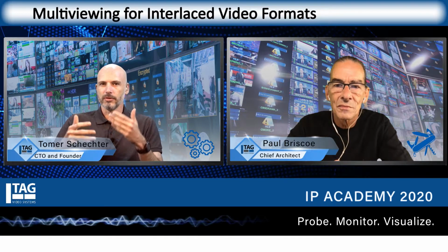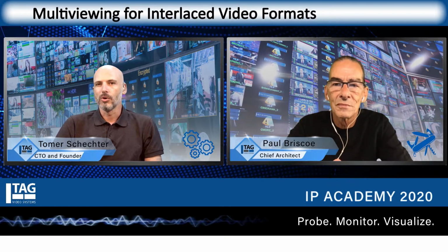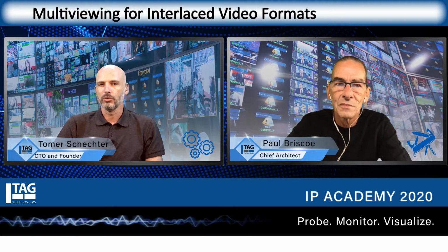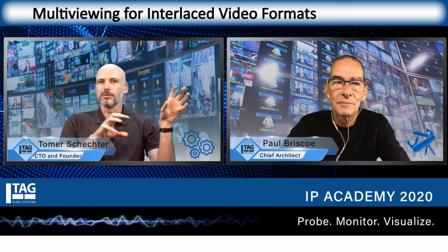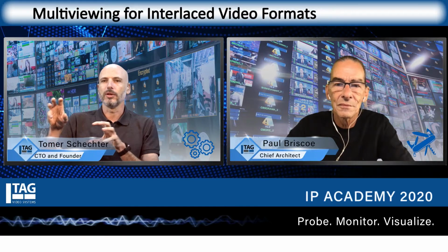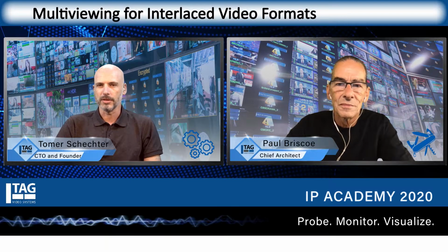Because still you have the issues of the different positioning of the lines. And I think that the more sophisticated one is really to do a motion compensated algorithm where you detect specific items moving in the frame and do the interpolation of all of the missing information. Then you'll probably have the best quality for the moving stuff in the image.